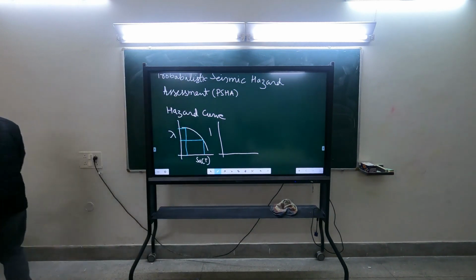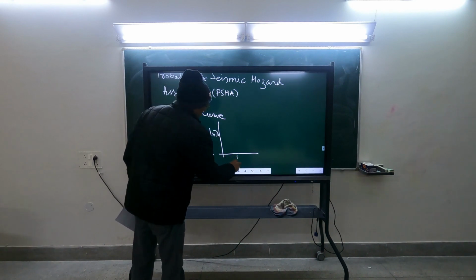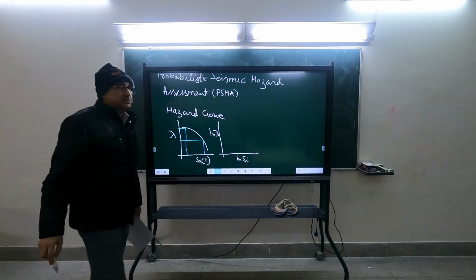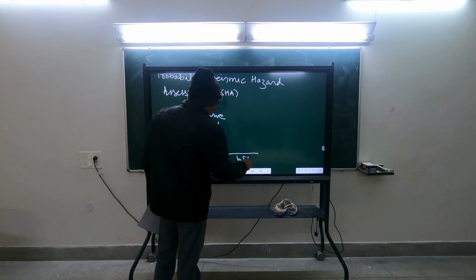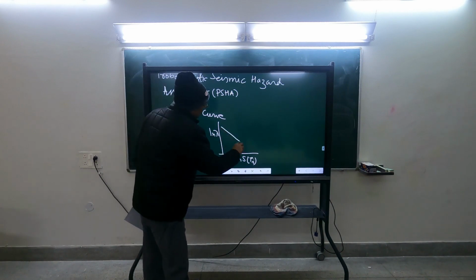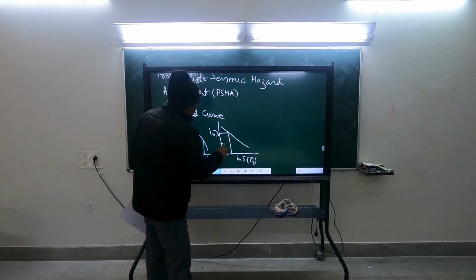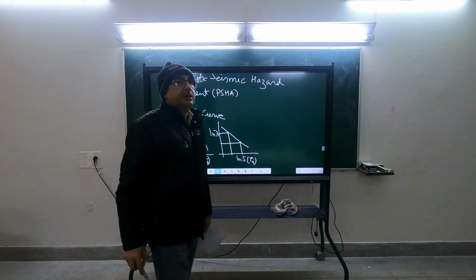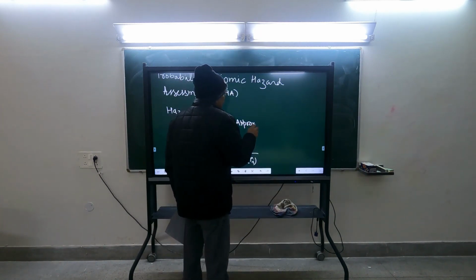Let me check whether it is, the equation is given in natural log. Yes, natural log. So if you take, okay, Si means S at any period Ti. So at a given period it is there. So this is approximately linear. So if you know this value at 2 probabilities, at any other point you can calculate. But keep in mind, this is an approximate relationship. Actually it changes from site to site.